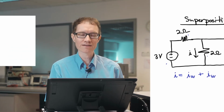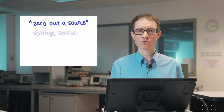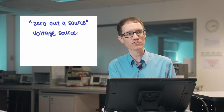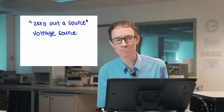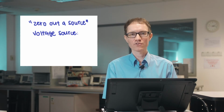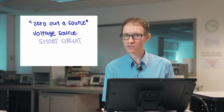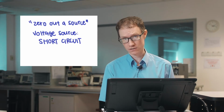In order to do that, I have to zero a source. So how do you zero a source? Well, imagine that you have a voltage source and I say zero out the source. Well, you could imagine sitting in front of a DC power supply with a knob. You just turn the knob down to 0. In other words, if you've got a 6-volt source, turn it down to 0. A 0-volt source behaves like a short circuit.